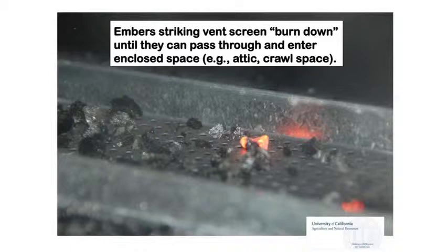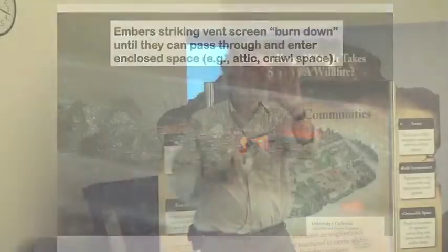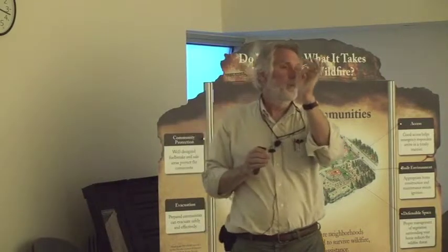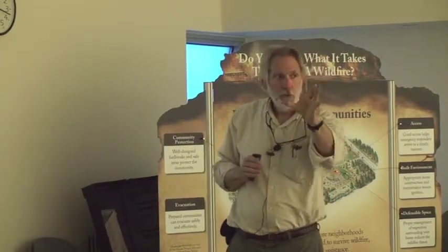So this is some testing that we were doing, and here's an ember. This is a 1/8 of an inch mesh kind of vent. Here's a hot ember sitting on top of a 1/8 inch hole, and there's air blowing by it. So in your case you could have an ember landing against the screen of your attic vent, and with air blowing on it, it'll just burn down. Assuming you have a screen, it'll burn down till it can fit through it and go through.